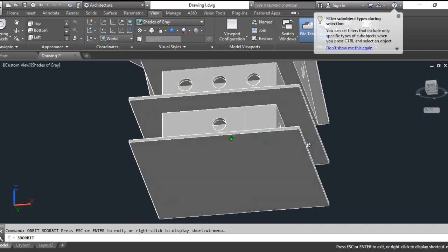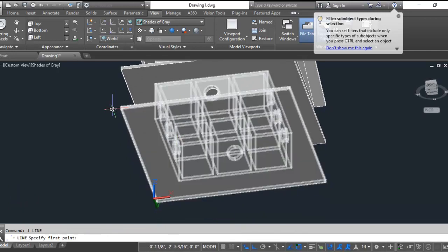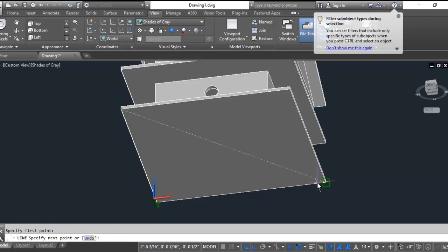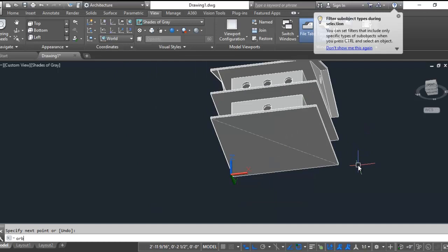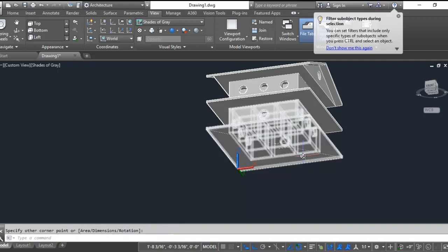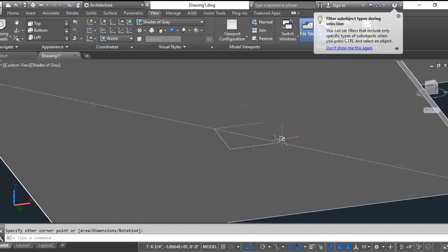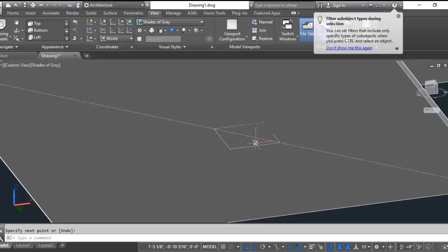Now the last thing to do line work wise before we start applying materials is put a post on this guy. So I'm going to put a line across there just to find the midpoint, and then I'm going to draw a rectangle. My dynamic UCS is on, so I can do it down here. Dimensions are 3.5 by 3.5 for a 4x4. Now to get that rectangle perfectly centered, I need to do another series of lines from corner to corner of the rectangle. And now I can move the rectangle.